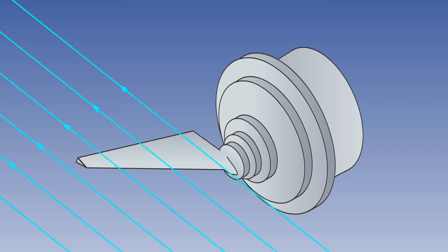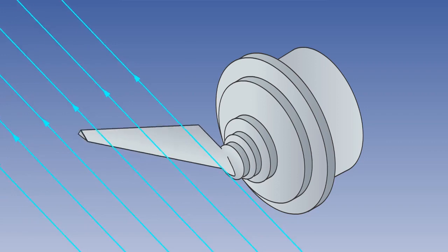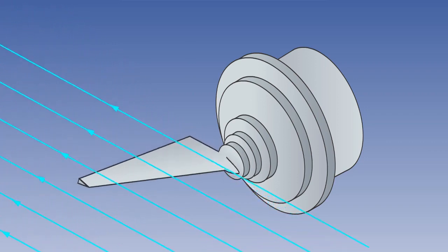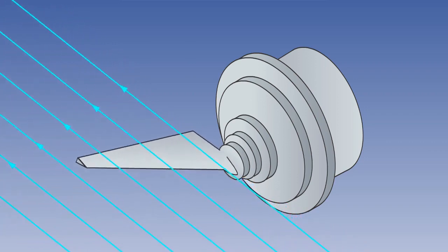In flight, the vane will take up a position which is parallel to the airflow passing over it. Changes in the airflow direction will therefore cause a rotational movement of the vane and an attached rotor. The rotational position is transformed by a transmitter into an electrical output, which is proportional to the angle of attack.